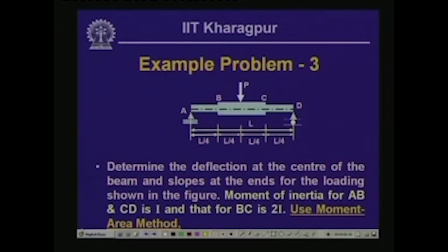Well, let us look into another example of variable moment of inertia when the beam is a simply supported one and is subjected to a concentrated load at the center. Now, as you have noticed, for this we get the bending moment diagram, where the maximum value of the bending moment is at the center, and thereby in the central region, if we have the moment of inertia of the section, here this part is I, this part is I, and this part